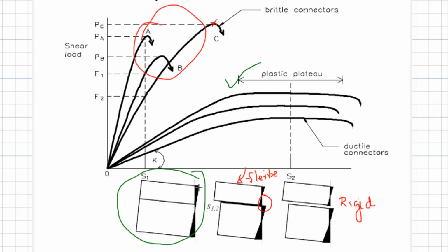This is the strain diagram, which is one for the entire beam. However, if there is a slip which I allow, then I'm allowing a small tension-compression system. And if this is concrete, the tension part will be neglected as we assume it is cracked. So even here you can see they behave as two independent systems.